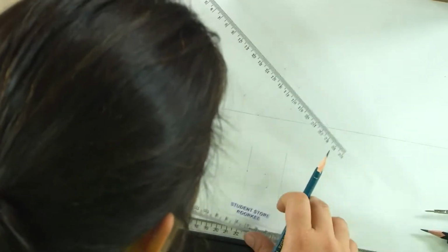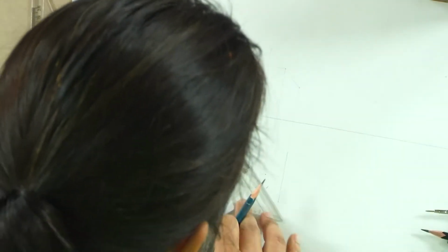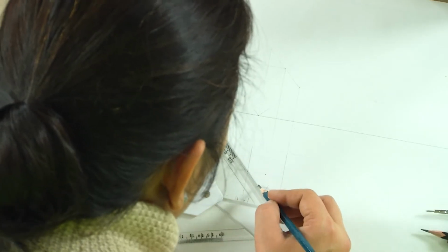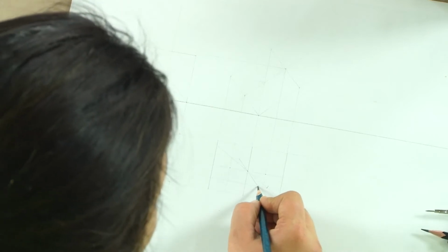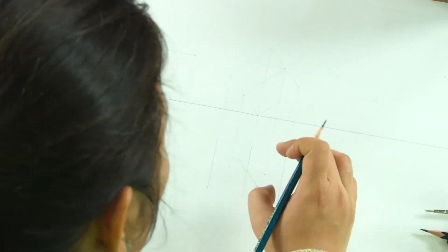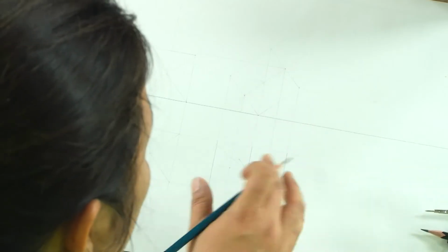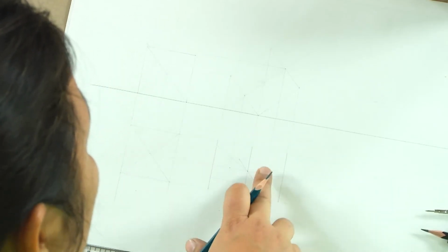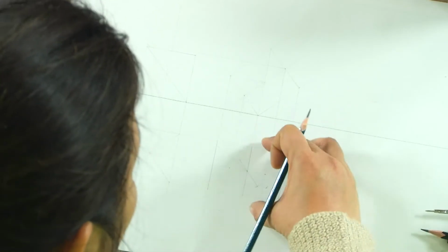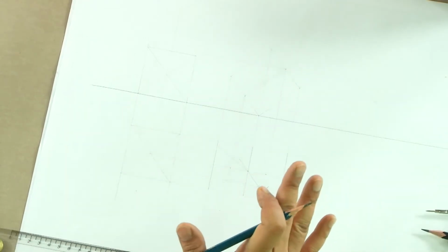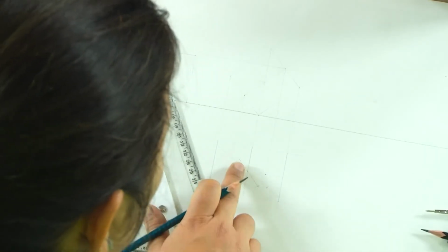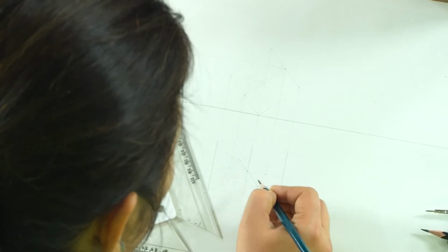So we have an axis passing through this point and having its trace there. This entire cube is rotated in such a manner that this axis now occupies this position. The rest of the drawing will move about this axis, and we will get a cube which is rotated in such a manner that the axis makes an angle of 30 degrees with the VP. So this is the revised axis, which is what we have got.